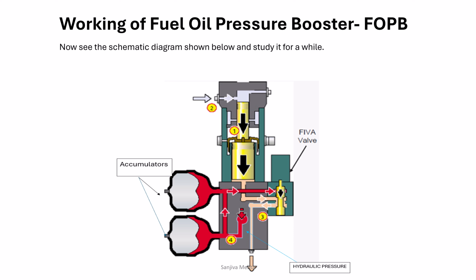The accumulator. Accumulators are needed because hydraulic oil is used intermittently. There is a nitrogen charge, and there is also a method to check the pressure and all these things. Nitrogen charge: you have nitrogen bottles on the ship. So this you also have to study. This is not part of this course, but we can always discuss it if you need such a question.